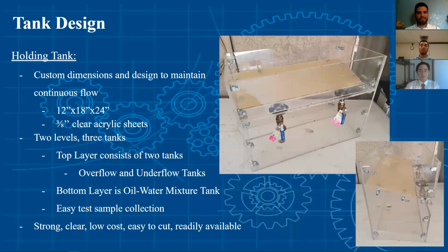Metal brackets, bolts, and nuts were used to hold the tank together. Furthermore, to prevent any leakage, thread sealant was used in each bolt, and an acrylic sealant was used in all of the inner edges of the whole tank assembly.